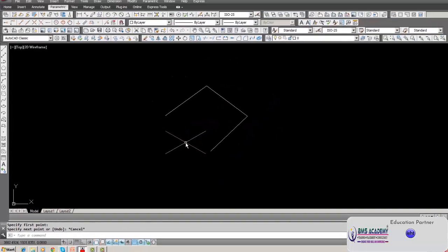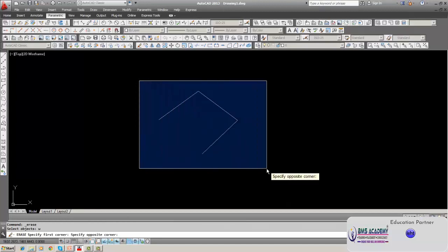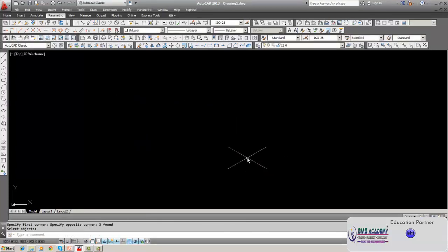What I just forgot to tell you one more thing, because we are getting an error here because its orientation of movement is not correct. So we manually adjust it, so it is not correct. The best way to do it is to select the ortho mode. We have selected polar tracking, so the lines will not clearly have an orientation in the isometric view. So better we select the ortho mode. It is always better to understand that in isometric, ortho mode is to be selected.